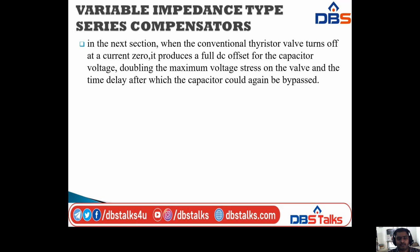In the next section I will discuss that when the conventional thyristor valve turns off at a current 0, it produces a full DC offset for the capacitor voltage, doubling the maximum voltage stress on the valve, and a time delay after which the capacitor could again be bypassed. So in the next section I will discuss these things, and also the remaining two variable impedance type series compensators, in the next class.